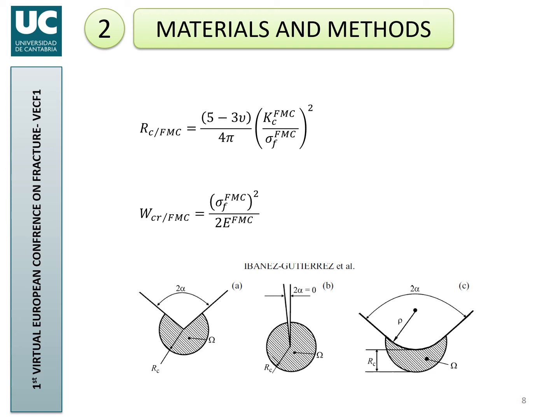The control volume is given by this R shown on the upper part of the slide, which depends on the fracture toughness and the ultimate tensile strength of the fictitious material, and the material capacity to store the strain energy density is given by the second formulation.